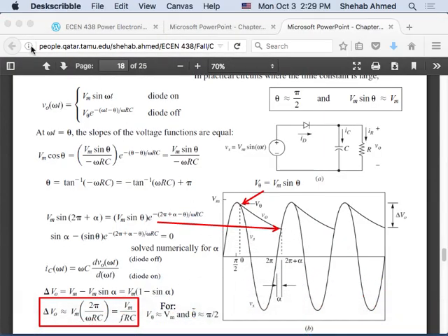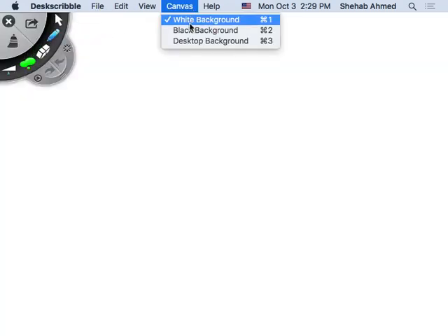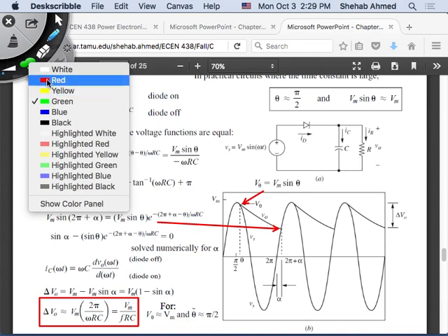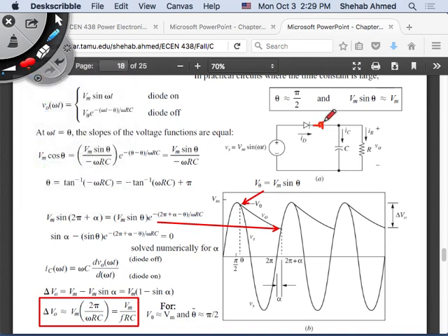So we will see later in another chapter that sometimes we add an inductor here. What does this inductor do? In this case, the inductor will smooth out the current. Because there's an inductor, can current rise abruptly? No, current will rise slowly.